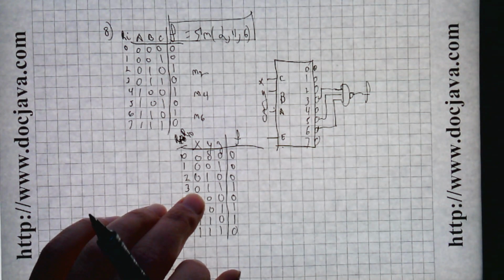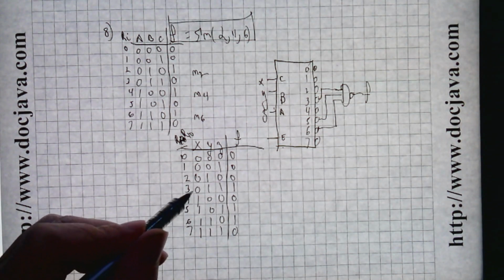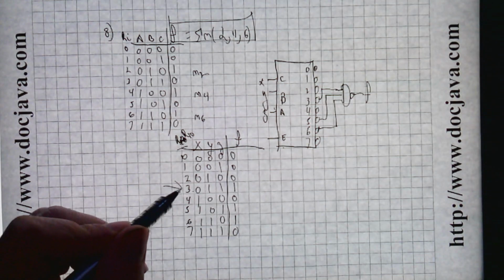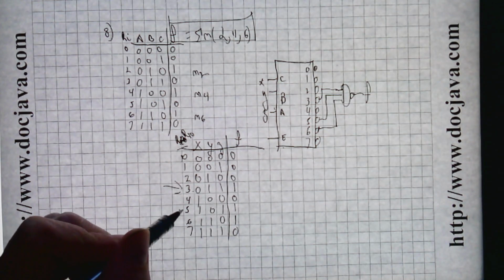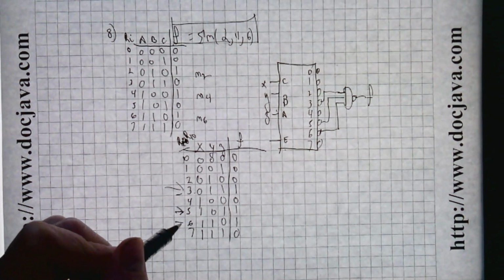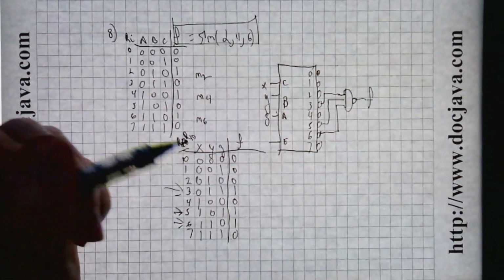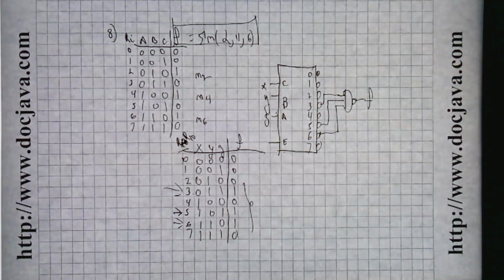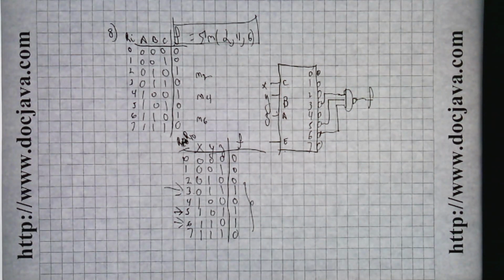Then it says 1 out of 3 inputs are logical 0. So that's here, 1 out of 3, and here, 1 out of 3, and here, 1 out of 3. So based on the truth table, I get an assertion of F equals 1 if 1 out of the 3 inputs are logical 0. What do you think of that? Does that sound sort of reasonable?